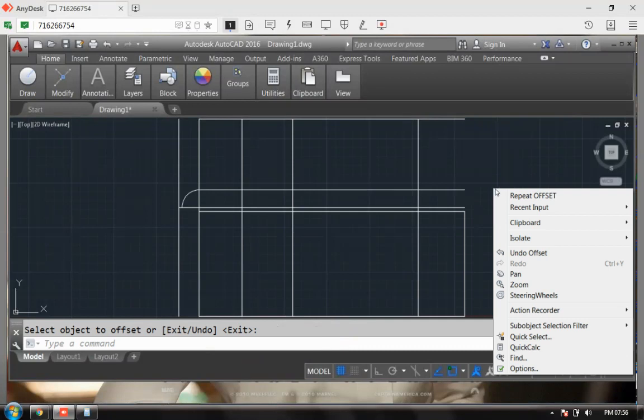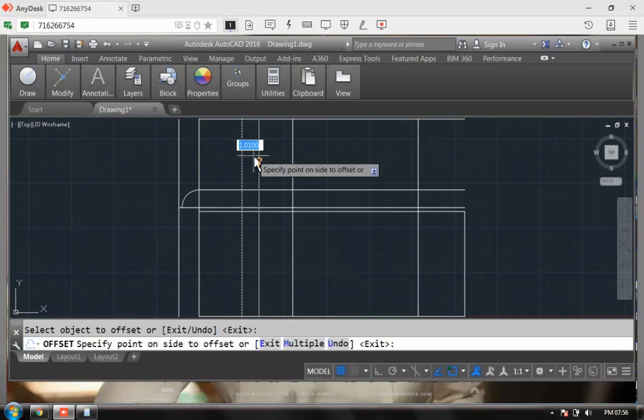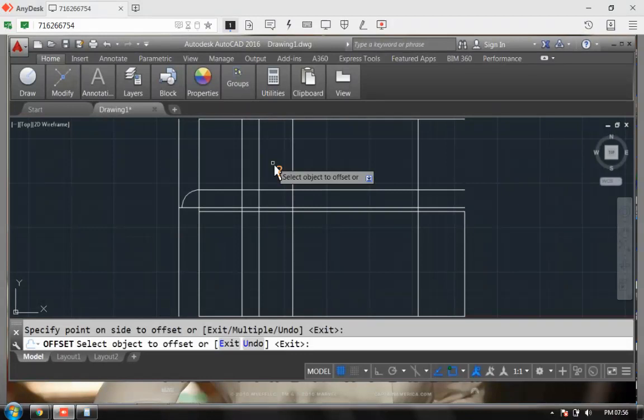We'll be using the repeating offset command. So my distance is now 1.01. Fine. Then to offset this, this location is done. Now, if everything is done, we have to go for one more, and we have to create a wall of 9 inches from all the sides.